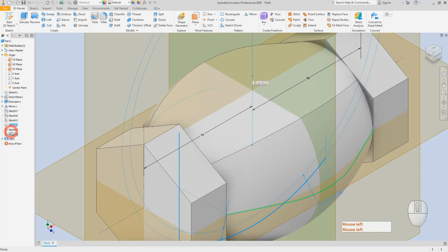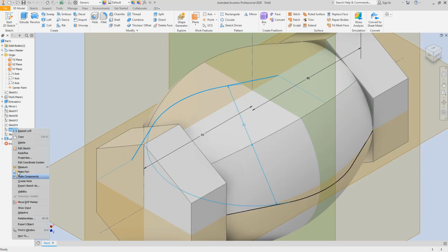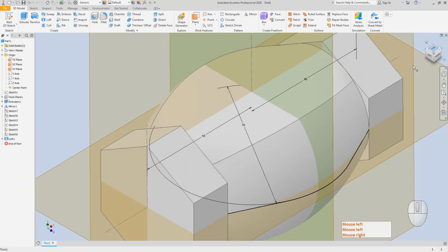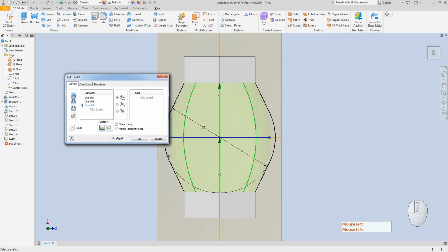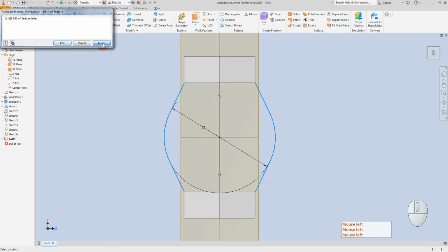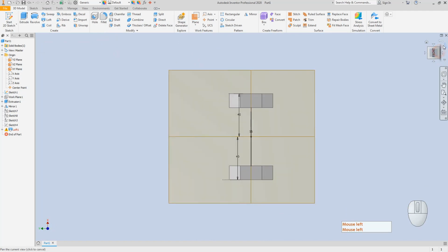When I have opened the pathway 3 and 4, as you see, we have not defined these lines and these parts are missing in our loft profile. For this reason, when doing these profiles, I will include the rails like this and also another rail on this side. Let's create at this point.